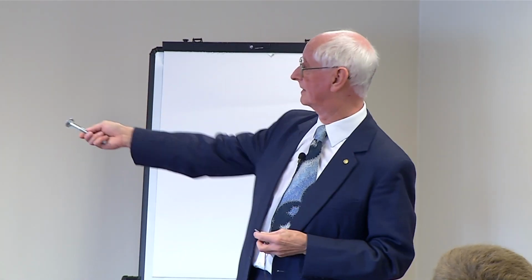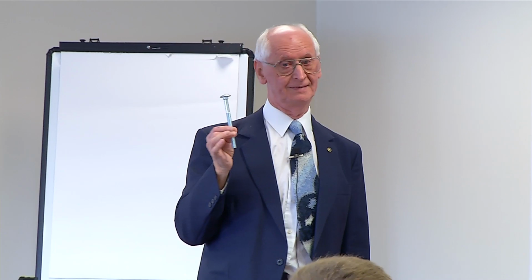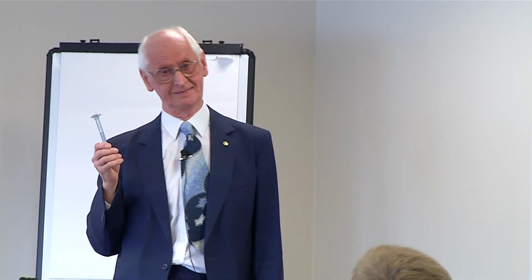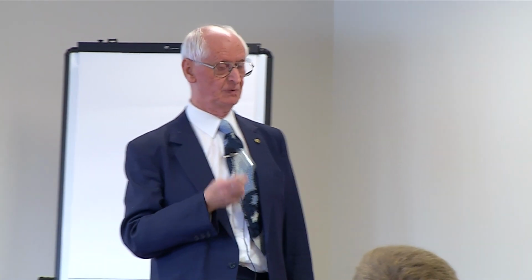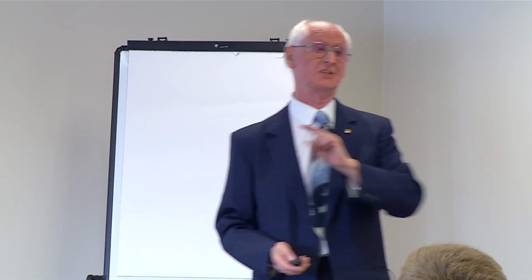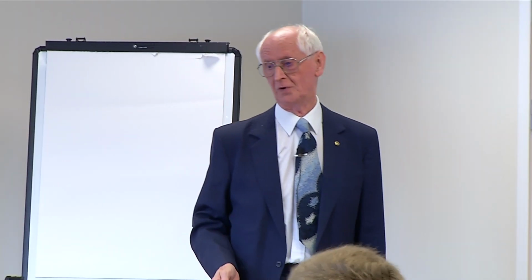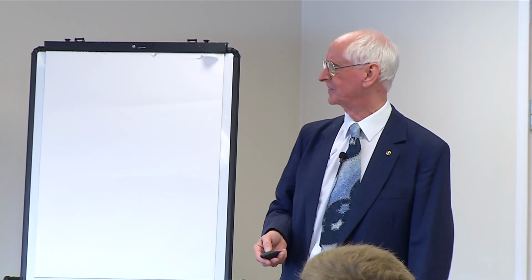So that is why this is written in red. They are not a structural bolt and should not be used for structural purposes. The clue is in the name, coach bolts, invented for coach work, from the days of horse and carts and carriages, but greatly misused. So if you see any of those in a structural application, you need to flag it up as a big red warning. But we do also have sort of incompetence as well.